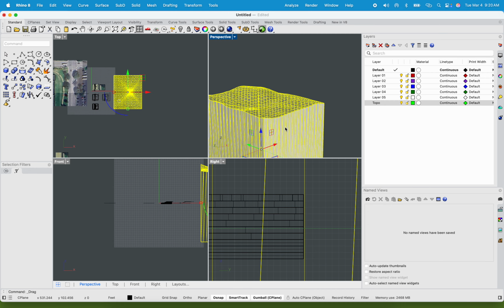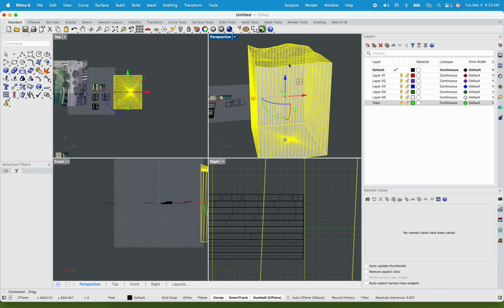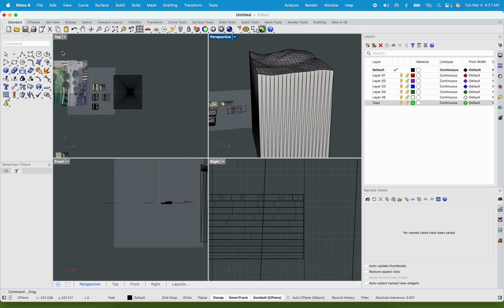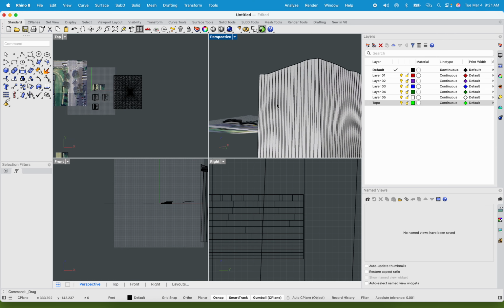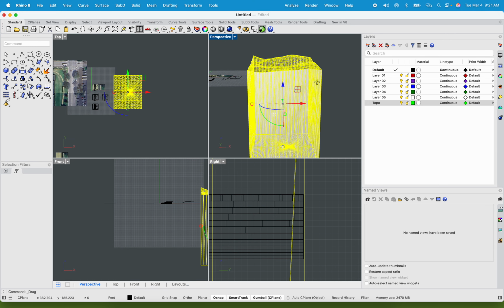To be fair, we could use that for this project too, especially if you want to use a fictitious place that's maybe outside of San Antonio, or maybe you don't have topography lines, right? How many of you guys have ever been in studio and you don't have topography lines of your location, right? You can find an STL, bring it into Rhino, and then of course contour it. So in our case, I'm going to chop off a significant portion of this just because that's kind of ridiculously huge. And I really just need that surface part. So in my case, let's trim it out.